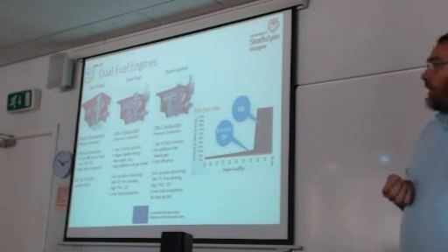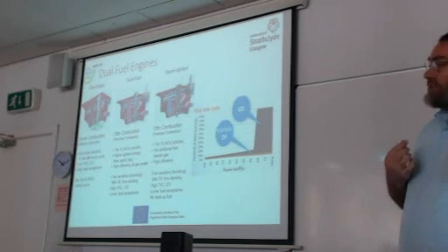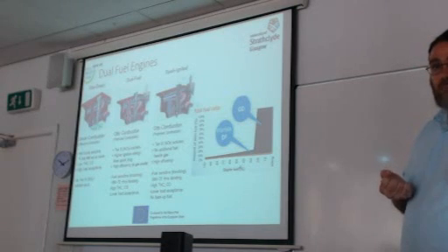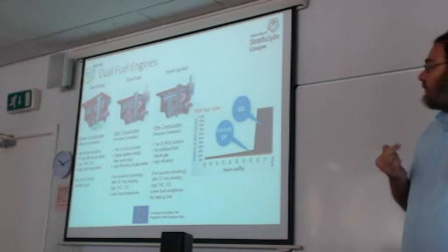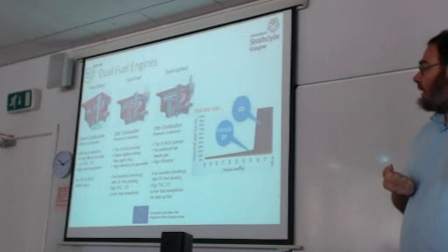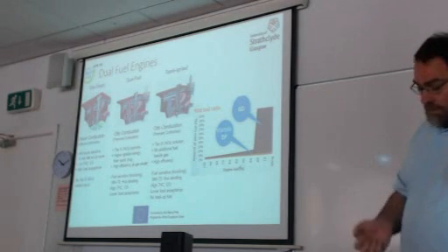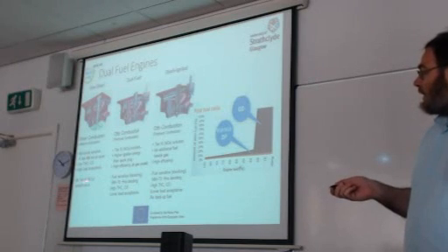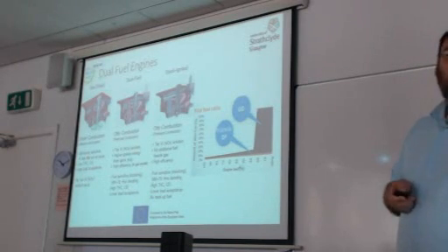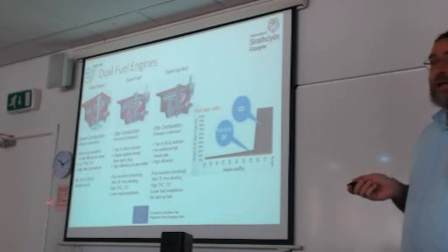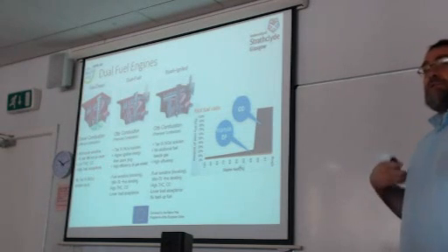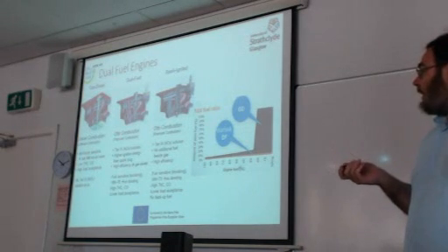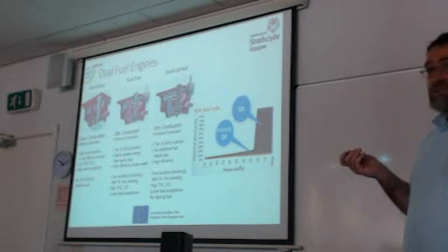Because the pressure is high. The engine operates in diesel mode, and you know that when the engine operates in diesel mode, the compression pressure and then the combustion pressure are high. And when the pressure is high, this suppresses unburned hydrocarbons and the production of carbon monoxide. But the disadvantage of this high pressure and of course high temperature is that NOx is high.